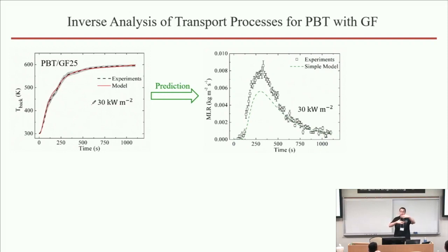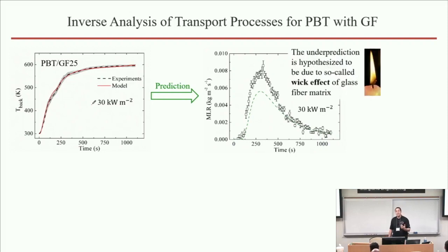the heat release rate actually jumps up, instead of coming down as you would expect, because seemingly you dilute this material with an inert substance, right? You should have less heat release rate, and it goes up. The speculation put forward is that the glass actually acts as a wick. In other words, the glass residue, the scaffold left behind as the molten polymer burns off, helps wick the polymer towards the surface. So you have a little pump inside the material that brings this molten polymer to the surface. It vaporizes, and as a result, you have that peak, right?